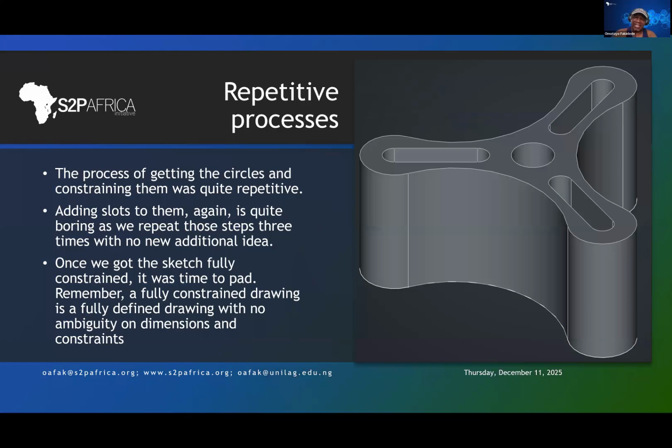When you finish that sketch and you get everything green, which means it is fully constrained, what do we mean by degrees of freedom and full constraint? Degrees of freedom are degrees of uncertainty about your drawing, things that are changeable, things that you have not told FreeCAD precisely what length, what angles, what radii, what diameter, what vertical distances they should have. So those are degrees of freedom. When you specify everything in a consistent manner, your drawing is fully constrained. Fully constrained is a euphemism for saying your drawing is fully defined. So instead of fully constrained, understand that to be fully defined.